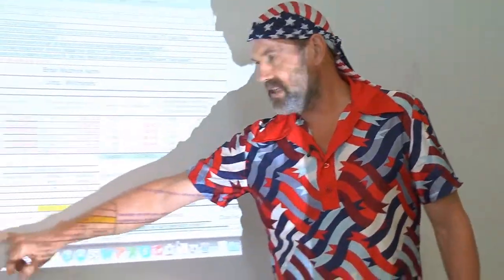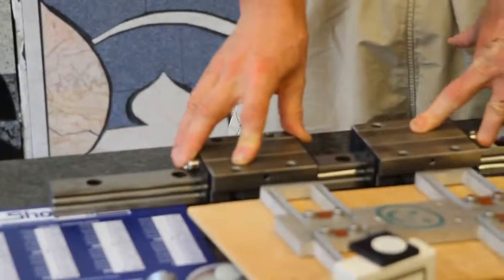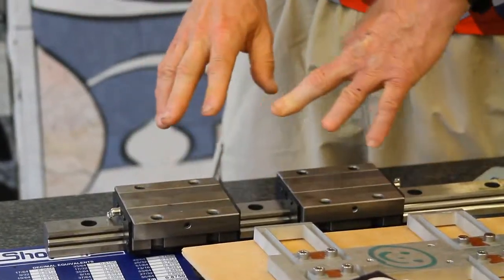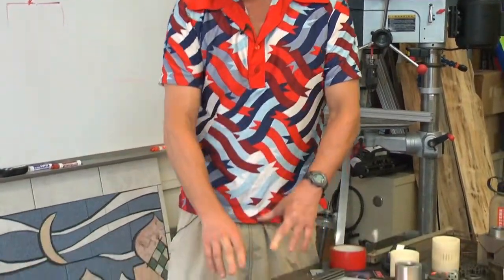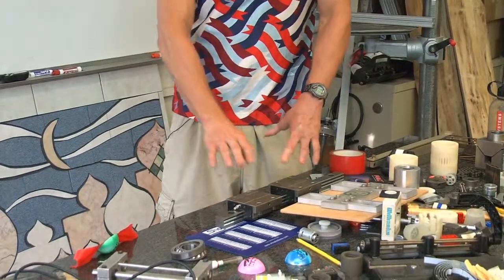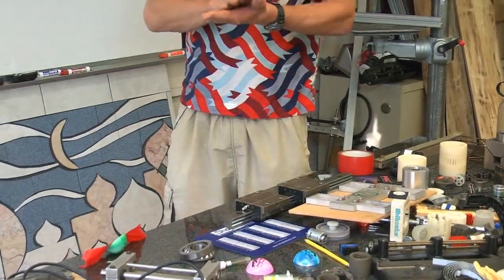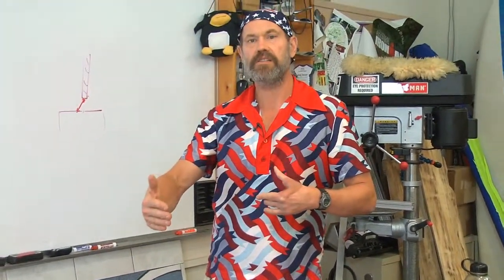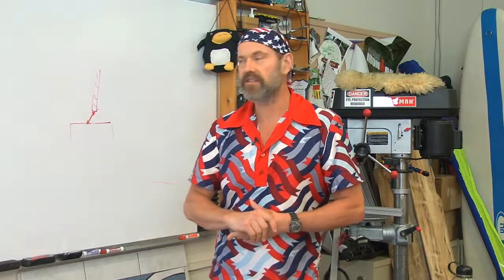The random errors are always entered in based on the type of logic we talked about before, for example, these moving carriages. Now, you're not limited to moving carriages of these modular types. You could also do a similar rationale of estimating the types of pitch, yaw, roll errors if you had sliding contact bearings, again, based on the spacing between the bearing pads and the types of tolerances you would incur for each of the bearing pads.